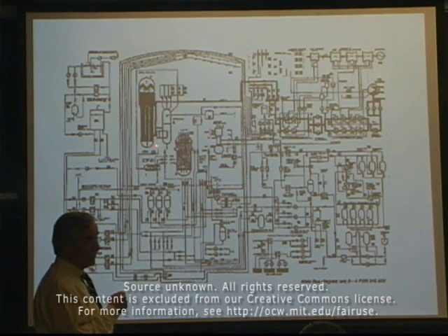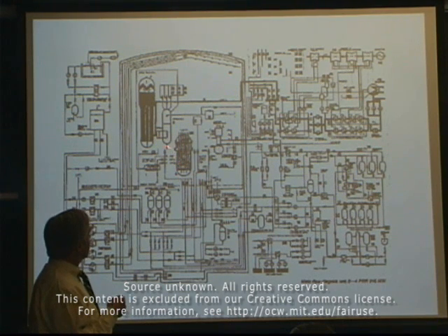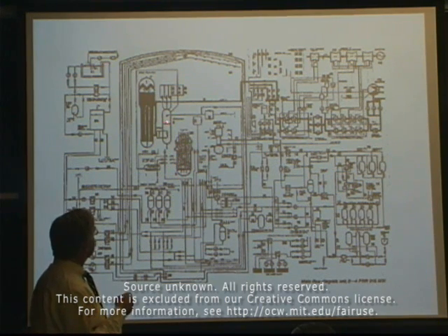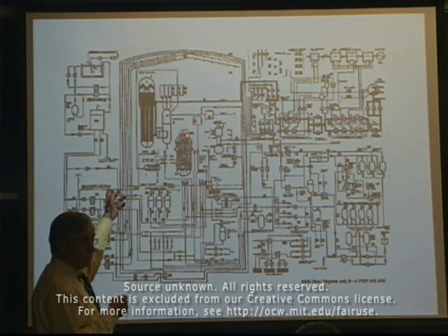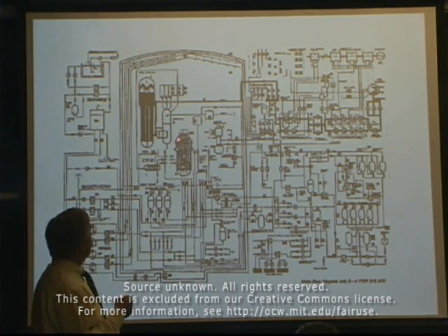Okay, very simple concept. And we went through the precursor event of Three Mile Island, which was Davis-Besse, again. The students were getting it. They were saying, well, if you lose cooling here, the water in the reactor expands, expanding the water in the pressurizer, which shows you've got plenty of water in the core, when in fact you were losing it. Confusing signal, right?